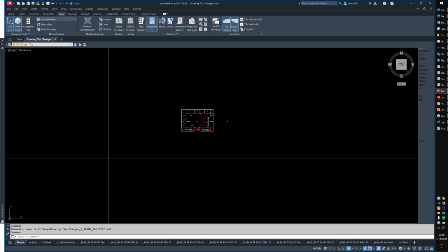You can type in -export to AutoCAD 2018, and it will create a stripped down version of your drawing. It will export everything, clean as much of it up as it can, and give you a basic AutoCAD geometry drawing.